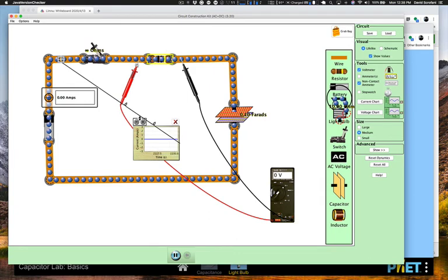The voltage drop across this resistor is in fact 120 when this is 0, and then they flip-flop. But before, with that little bit of internal resistance inside the battery, there was a voltage drop inside the battery across that resistor. So this guy here was never really 120. It was this resistor and the one inside the battery that were dropping the 120 volts. So now you'll be able to see this voltage start off a little higher than before. Here, watch. Yeah, see?